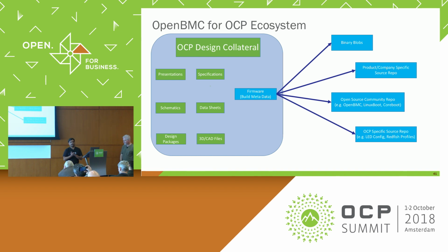For example, in the case of BIOS or open system firmware, you may want to download something from Intel FSP, and then use something from the coreboot project, then the LinuxBoot project. So you want to stitch them together, and the makefile should allow that. You should be able to download all these individual binaries, binary blobs, and source code from multiple open source projects, and then create a combined firmware for you. That's the goal actually. Hopefully next year we should be able to enforce this as part of hardware contributions. But that's where I think OpenBMC fits into this ecosystem.